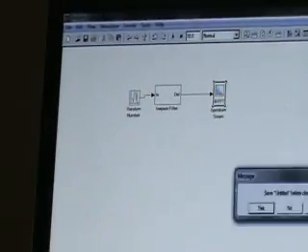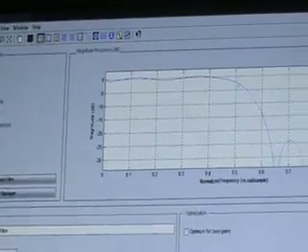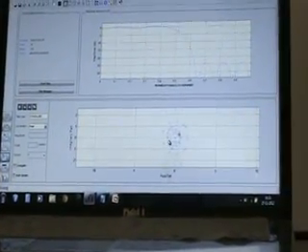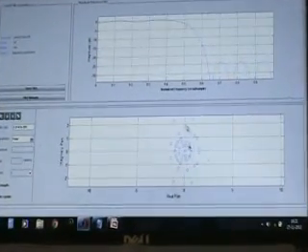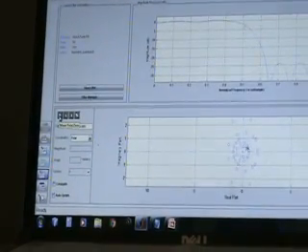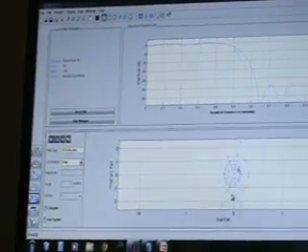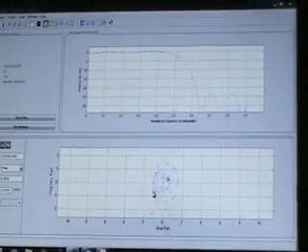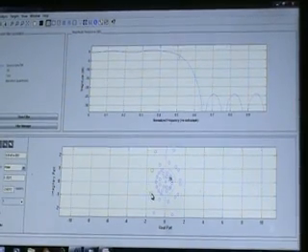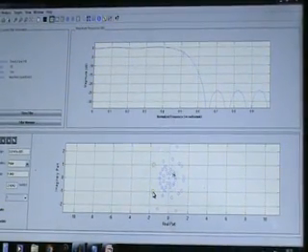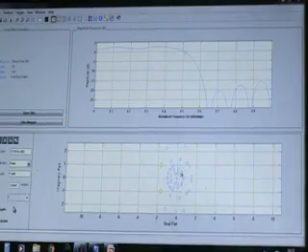Now coming to FDAtool again. In the FDAtool we have an option called pole zero editor. Once we click on this, we get all the poles and zeros of the filter which we have designed. The first option is move pole zero. This is used to move some poles or zeros of the filter. As these two are conjugate zeros, they move together.